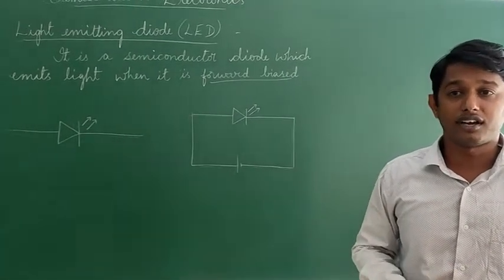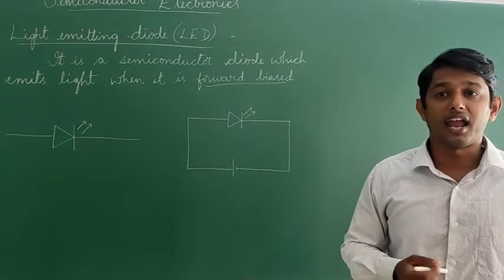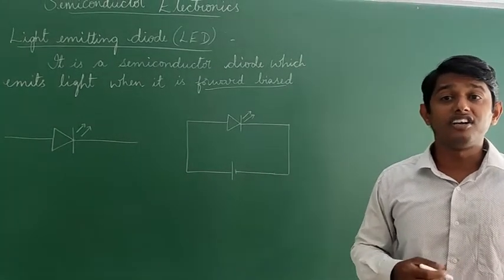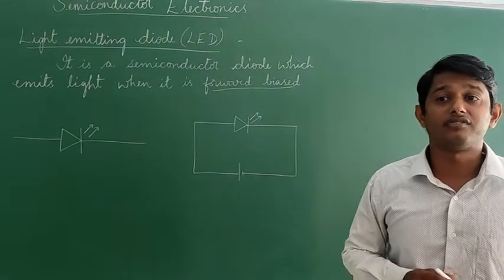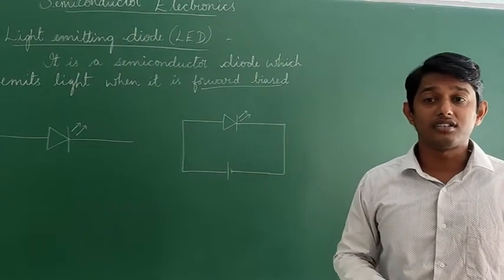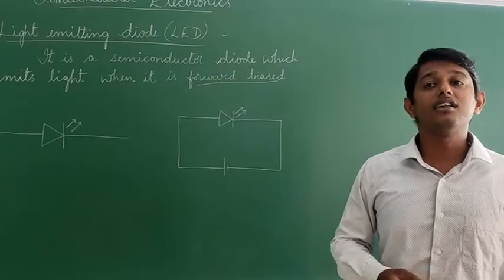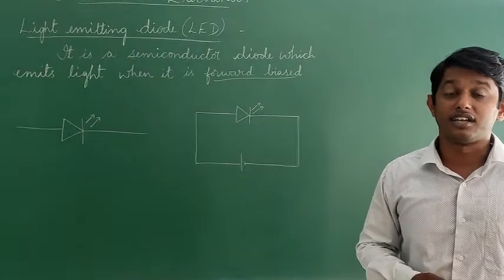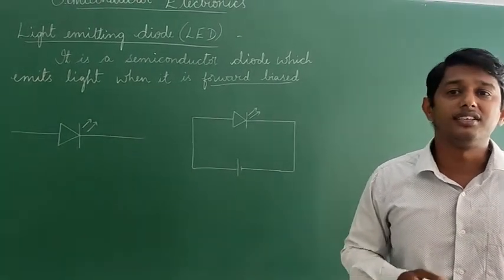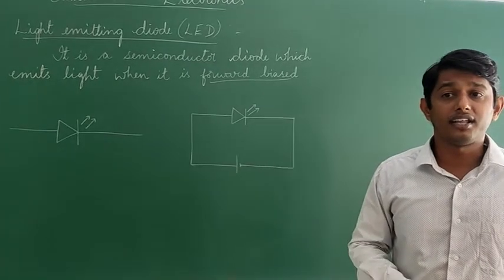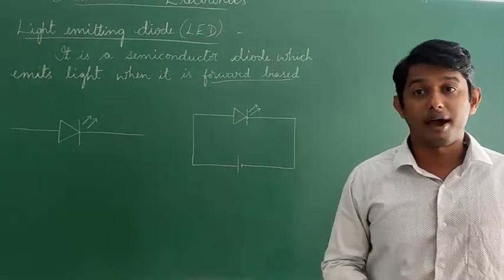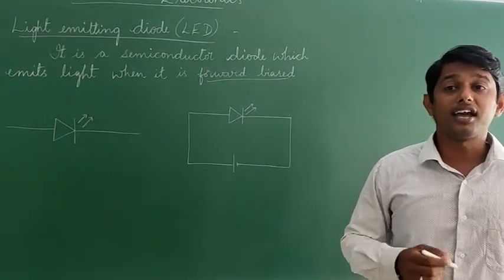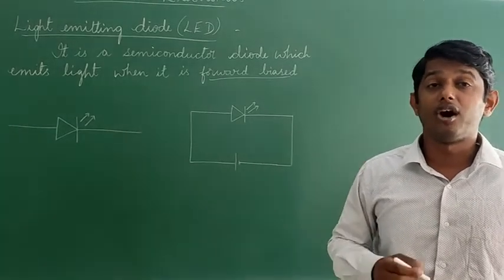When the forward current of the diode is small, the intensity of light emitted is very small. As the forward current increases, the intensity of the light increases and reaches a maximum. Further increase in the forward current results in a decrease of light intensity. So LEDs are biased in such a way that light emitting efficiency is always maximum.